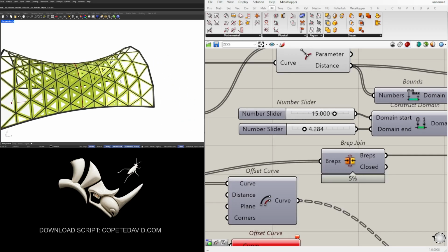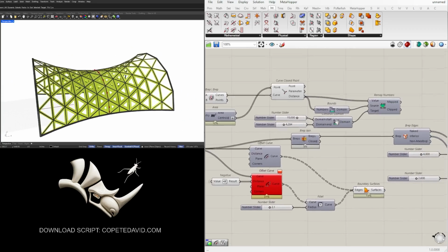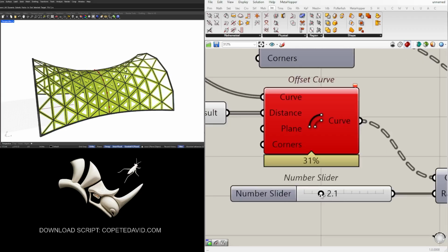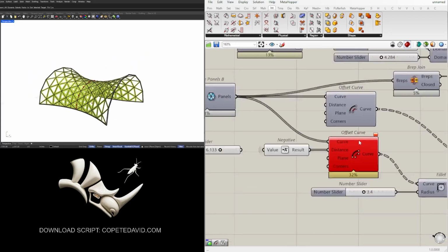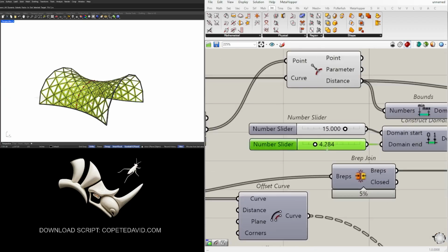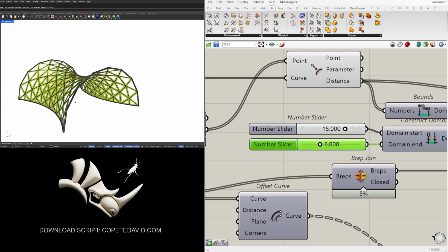All right. So I think that's looking good. The other thing we can do is increase the fillet here. And what happens when you increase it to a point here, they will become circles because they will create a fillet all the way around. We don't want to go too far. And then the minimum is the smallest number, which is right now at 4. Let's just go to 8 here. Or 6. Okay. That is looking good.